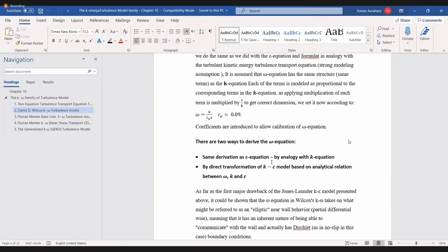So what we can see is that the theory for large eddy simulation is a lot more solid than that of Reynolds average Navier-Stokes. Of course, in Reynolds average Navier-Stokes, we get no turbulent content. We model all the turbulence. In large eddy simulation, we put a low-pass filter, so we get some of the resolved scales, and we model some of the unresolved scales.